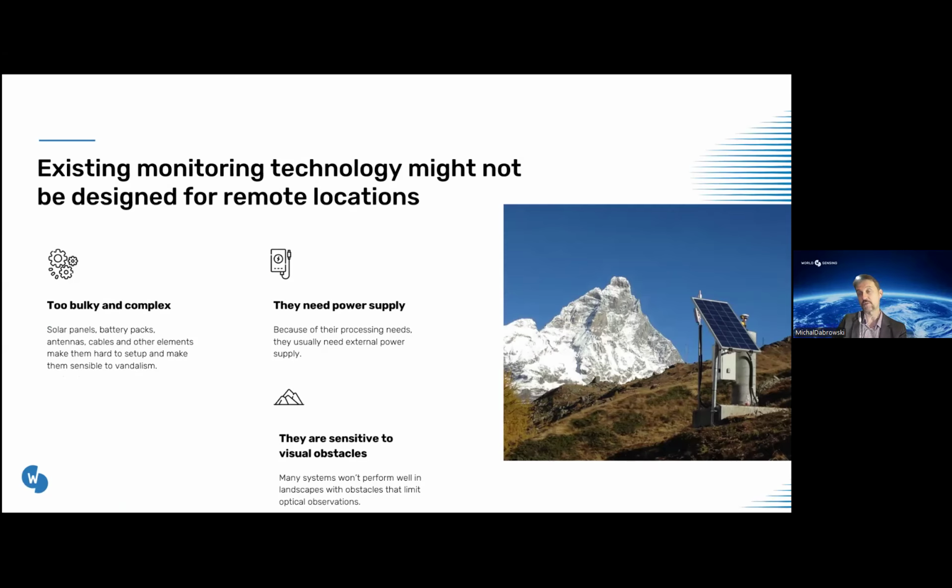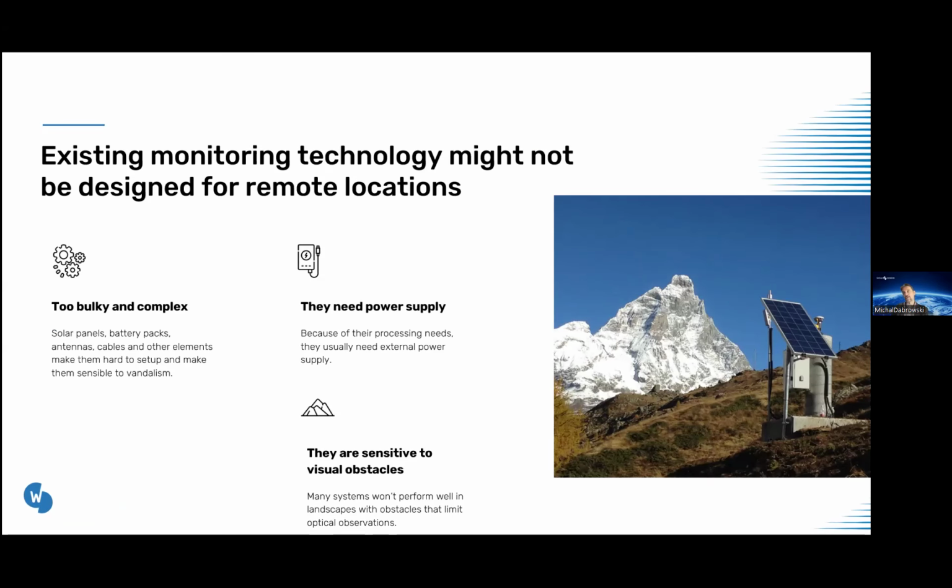Basically, when we monitor position, we monitor the state of the soil or the state of the asset, meaning that if it's supposed to be stable but it is moving beyond certain levels of agreed and confirmed safe parameters, such as thresholds, we call them thresholds, then obviously that can indicate that the monitored asset is prone to damage or is basically unsafe. So this is where we're utilizing the technology of GNSS.